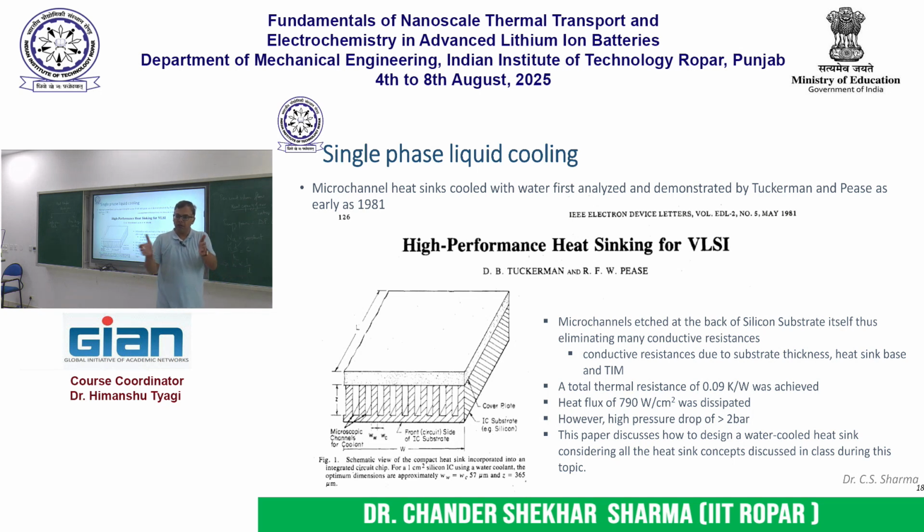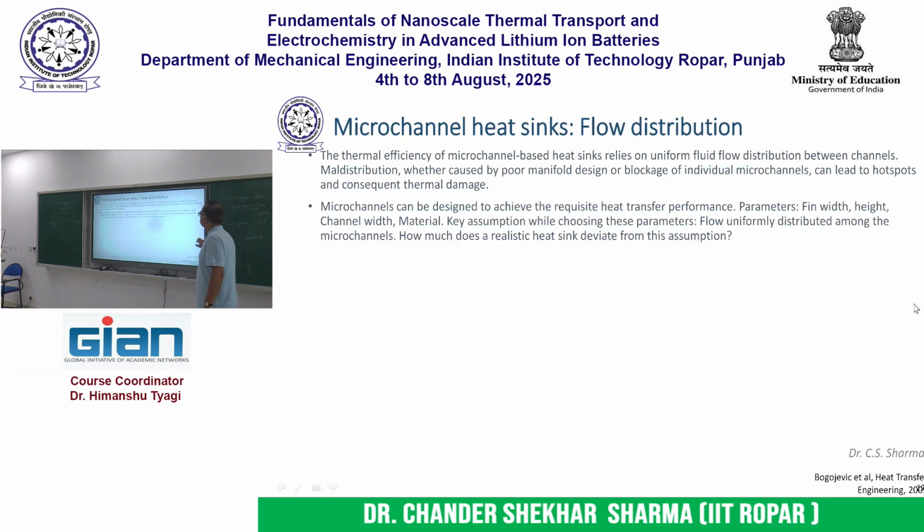So that's why I would want my coolant to flow through small microchannels which have small hydraulic diameter, so as to lift up the heat transfer coefficient that is available for heat transfer, okay. And if the heat transfer coefficient is high, then the same heat flux can be dissipated while keeping the temperature of the device low, okay. So that is why you see the use of microchannel heat sinks, okay.